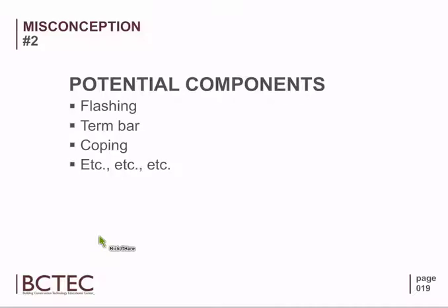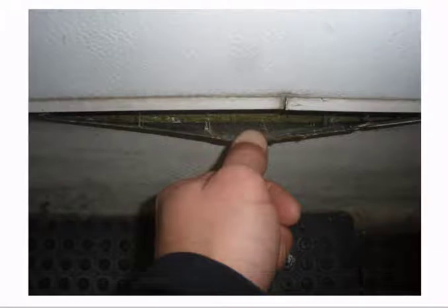Typically, Craig, we're not seeing a lot of problems in the field of the roof. Sure, you might have a hole or a puncture that's going to come up through the life cycle of that roof system, but mostly where we're seeing these problems are all the detail work. Seams being a big one, flashings, perimeter edges, drains, et cetera. That's really where our problematic areas are going to be.